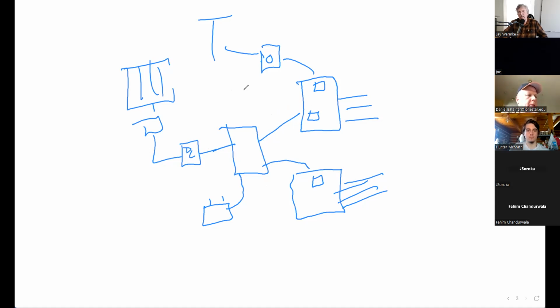But under the scenario where the grid is operational, power is flowing in all directions to all power. As soon as this unit senses the grid has gone down, it disconnects. So when everything's operating, it's going here and it's going here. But as soon as it realizes the grid is no longer operational, it's going to disconnect this connection point. Now the power is only flowing into the critical load panel. That way you can't backfeed the grid. There's no islanding that'll take place.